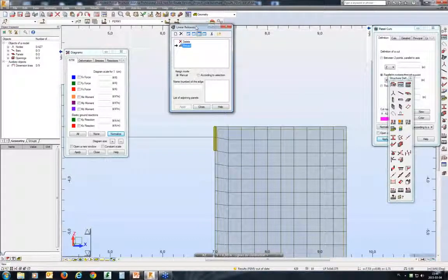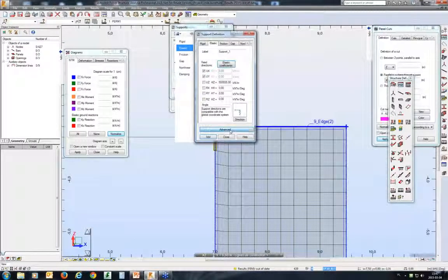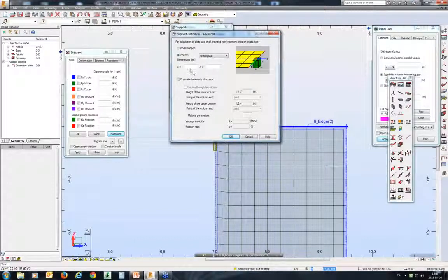All right. So, can I get the reduced forces above a supported node when the support is not a column or a wall, but just a supported node? Yes. In this case, when you define a support, you need to go to the advanced parameters and tell what the real size of the support is. The real size when you define a column is taken from the properties of the bar element, from the cross-section. For a nodal support, you should provide this information as the additional attribute of the support.